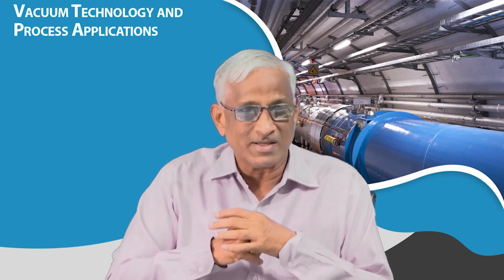Otherwise, there are very big particle accelerators of 1 kilometer diameter, nuclear particle accelerators like the LHC experiment, with huge chambers at 10^-8 torr. If it takes 2 months, 3 months to evacuate, then you cannot do any meaningful experiment. Anyway, I am giving all this because I want you to understand the importance of fluid flow in vacuum systems